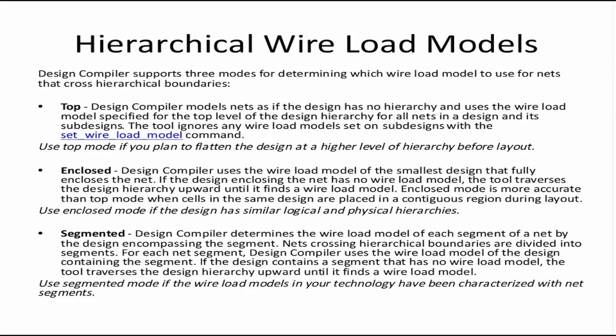So now, one is what wire load model to choose. Second is what is the mode. Design Compiler supports three modes for determining which wire load model to use for nets that cross hierarchical boundaries. Now, in most cases, your design will have hierarchy. So Design Compiler has three WLM modes. One is top.